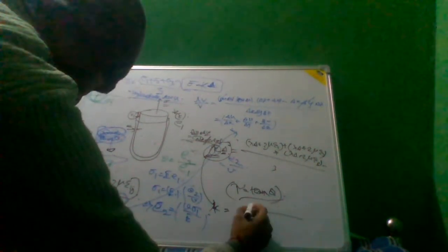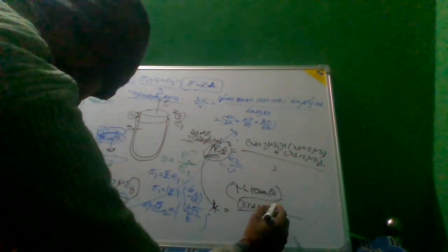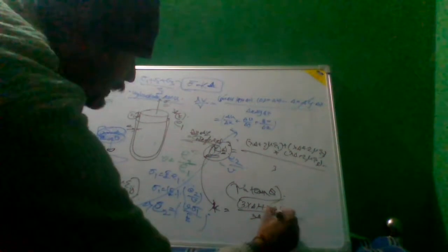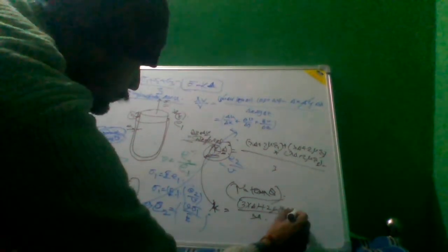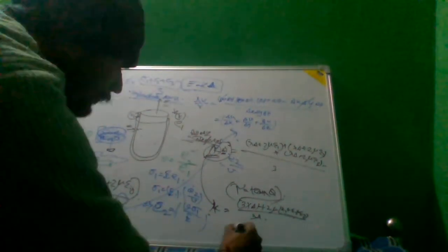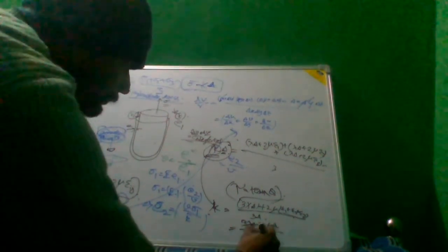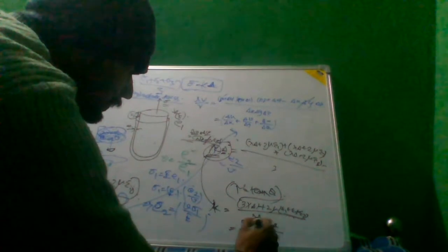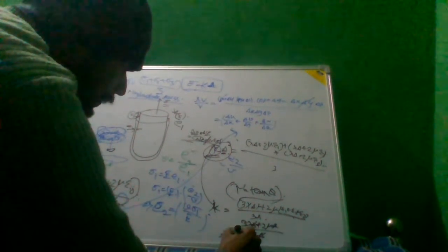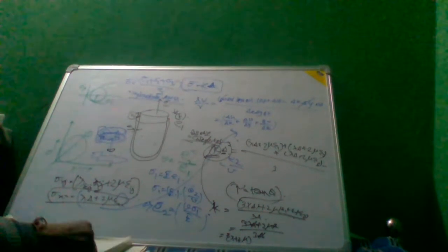3 lambda del plus 2 mu common into E1 plus E2 plus E3, and E1 plus E2 plus E3 is actually equal to the value of del, and the dels will cancel each other. So K is 3 lambda plus 2 mu divided by 3, totally depending upon the Lame's parameters.